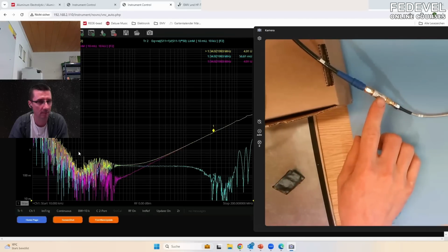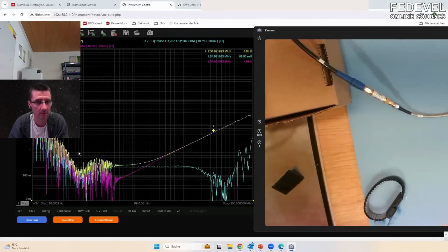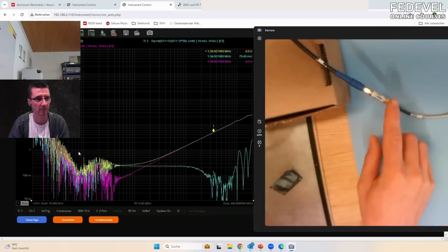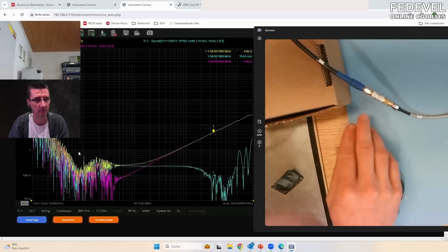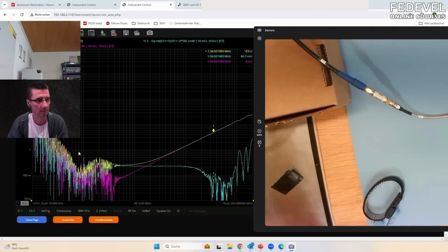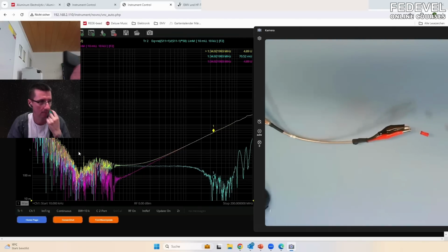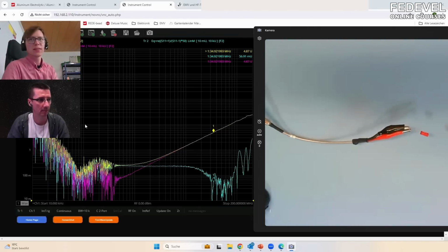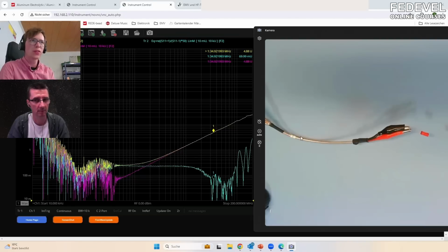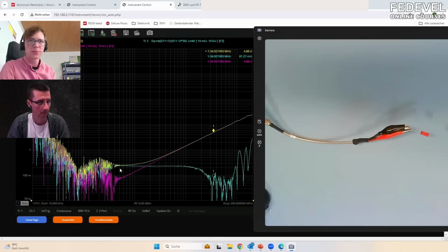And this limiter is also to protect it a little bit. I mean, it's not perfect, but it's for ESD, so that I will not destroy my device. And the frequency range is from 200 kilohertz upwards. This means it is also like a capacitor, and therefore it makes this measurement not so sensitive. So when I remove this one and calibrate again, I will get better results.